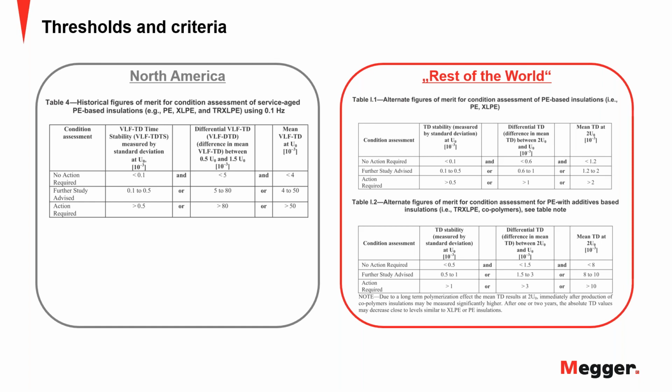And these chemicals basically are initially in the cable insulation. And so when you measure tan delta, you measure the dielectric properties of the polyethylene, but you also measure the dielectric properties of these auxiliary components, which means the tan delta is typically higher than what you would expect for pure polyethylene. So that's why it really doesn't make much sense to run it, even not to get this famous footprint, because the footprint may be higher than what you expect to see.